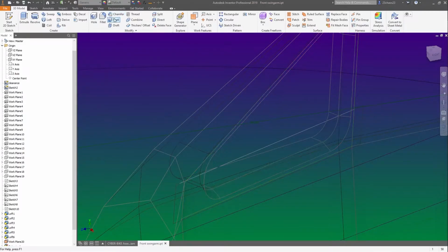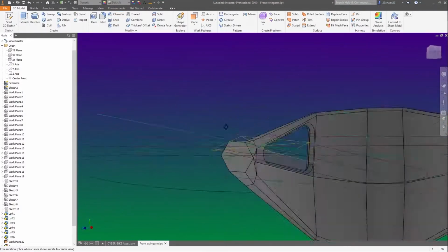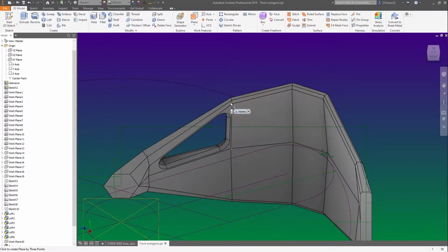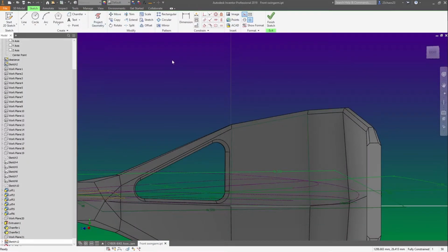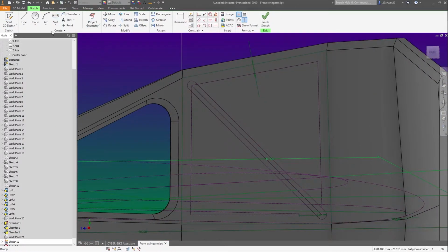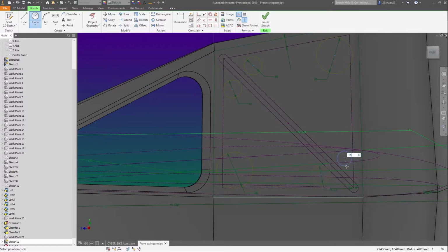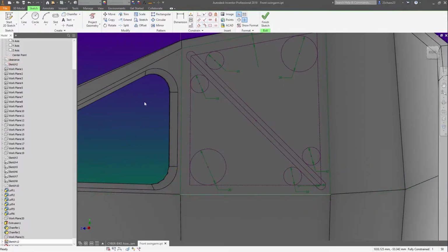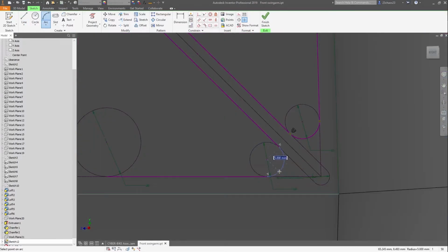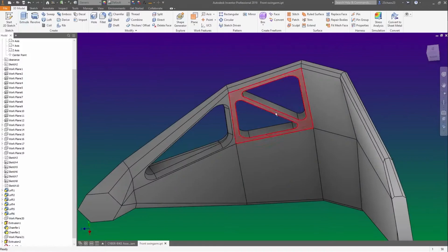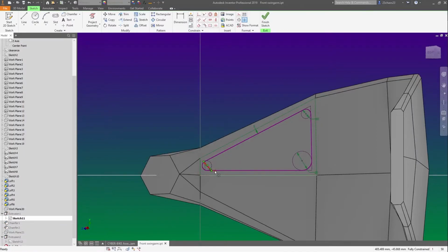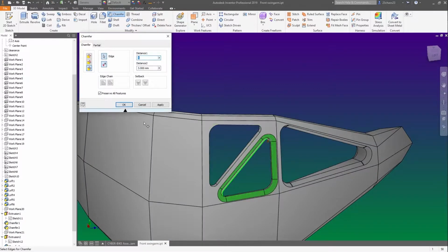Man, we can't do that. So I made this mistake of thinking I can do the cutouts myself and work out how I want to go about it. Now, for the most part, from the front to that first bend, it would have worked. These triangular cutout shapes would have generally worked. But it's around where it comes to the bend of the arm, where the forces change from being a linear transfer to being a torsional transfer, and you needed the material there in the bend and partway through the middle of the swing arm to stop the arm from twisting up.